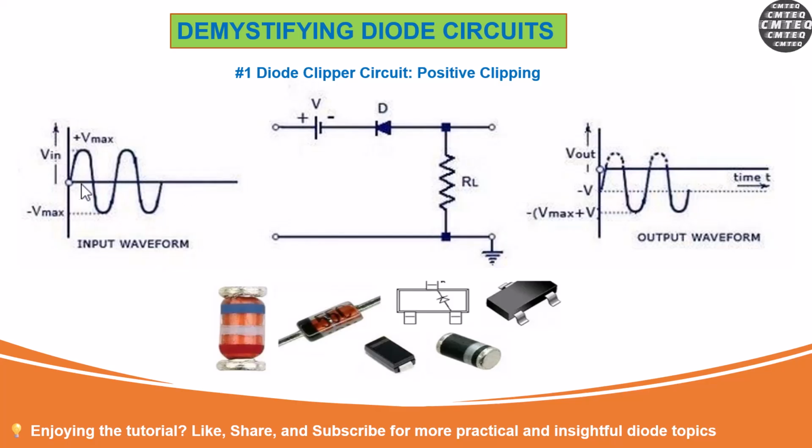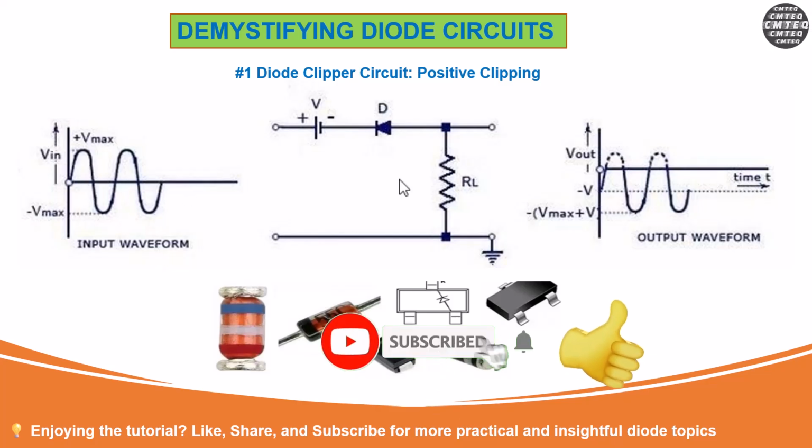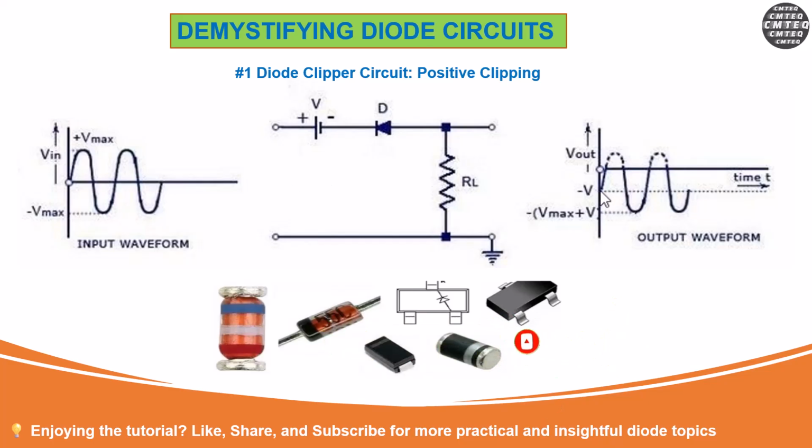So now, at the first positive peak, what's going to happen? As you can see on the output here, the voltage is starting to rise. Now we are assuming that this point is where the voltage increases to get above the set point of this voltage. At that point, the diode will become forward biased, and as a result, the voltage will fall flat here, and the excess voltage is basically going to be clipped.